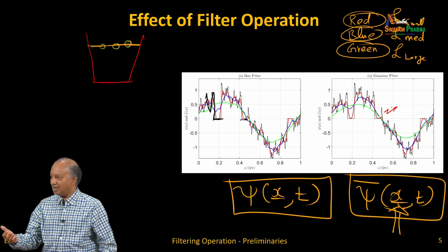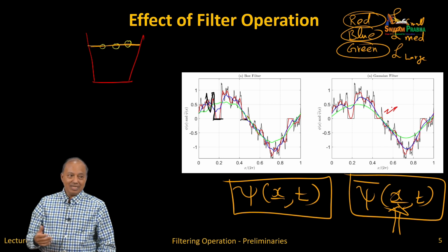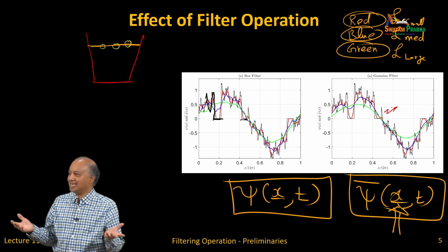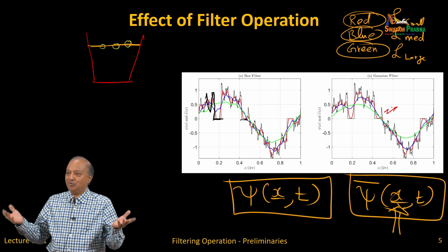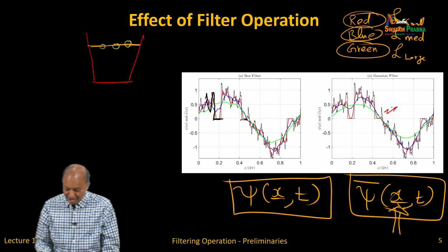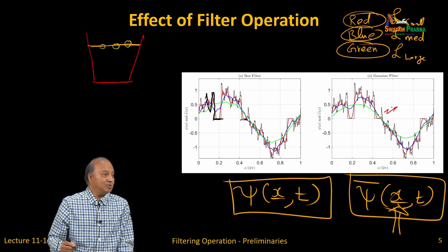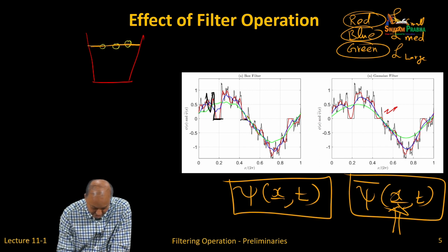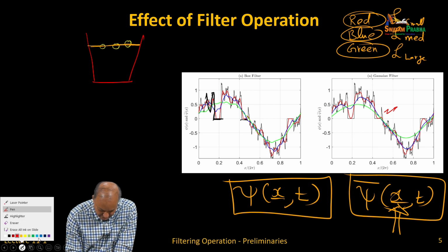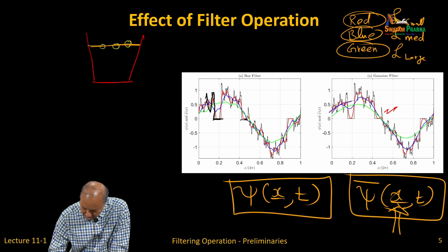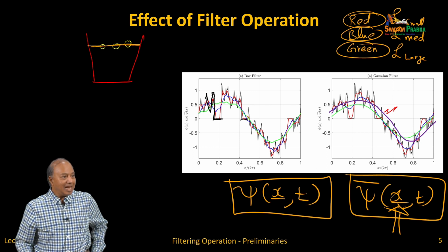That's how you derive a RANS model. The greatest advantage is that you don't have to tell what big L is. Unlike in LES, there is no filter. You're doing ensemble averaging. Now, in this case, the ensemble average, which has nothing to do with a length scale, may be like this. Let me pick a different color. An ensemble average.